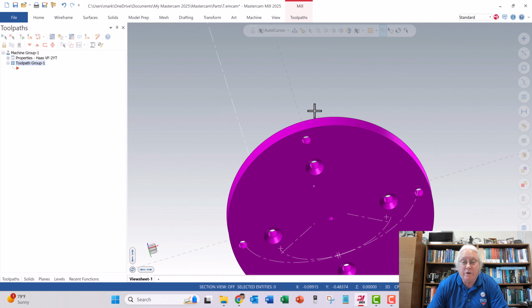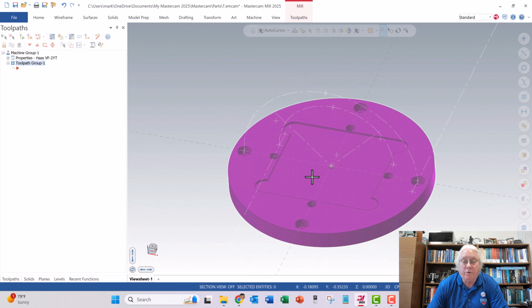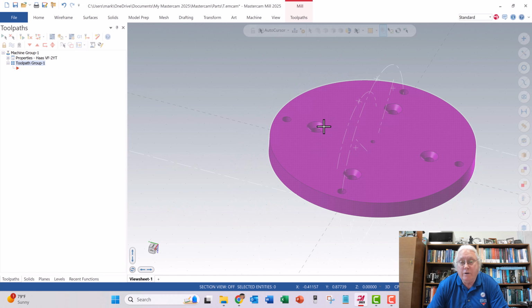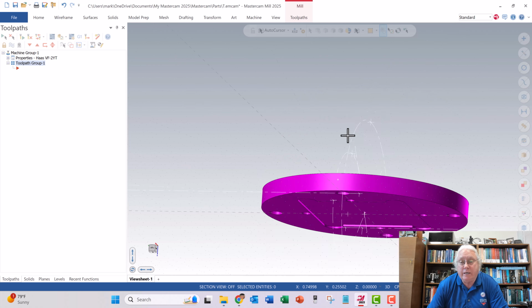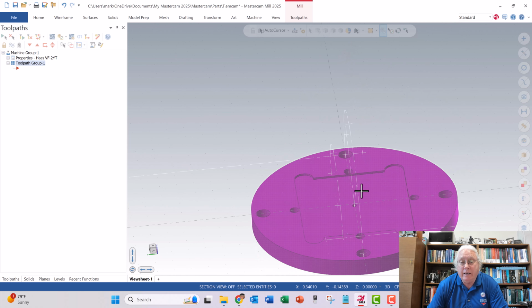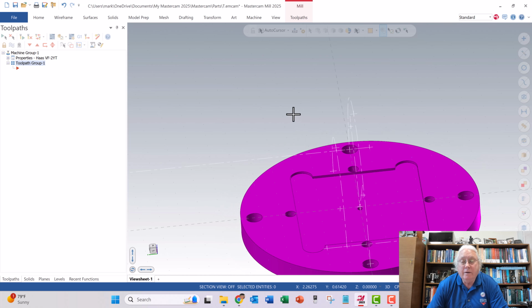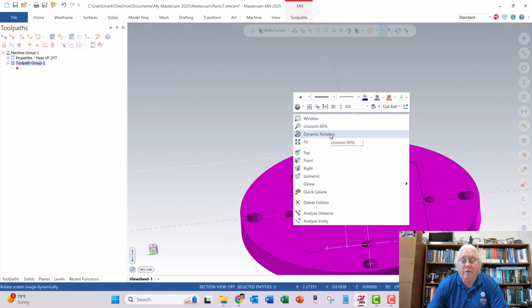Even though those are countersink holes, we'll drill through holes on the HAAS, take the part out of the vise, and then go take it to the manual mill and come over here and do these 4 countersinks. The holes are to be located. We'll just need to locate the tool on the manual mill to do the countersinks. And then I've also got a little hole here for a temperature probe, so we'll drill that from the top side as well on the HAAS.